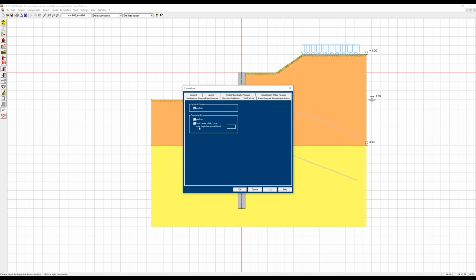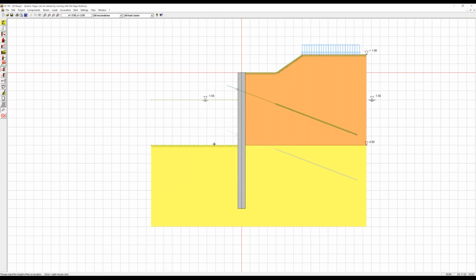And we can calculate the slope stability together with the program DC slope. But this should be, or mostly is, only calculated in the last excavation stage. So with this excavation, this anchor is now acting, it is used, therefore not shown in gray anymore.